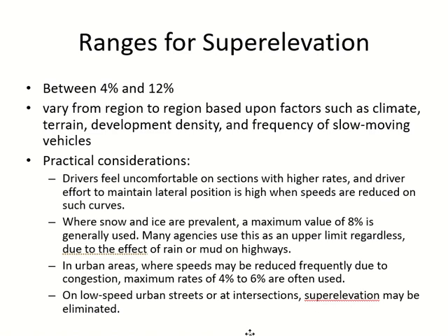Then the normal reactions are that you slow down, change your lane, or suddenly brake, and so on. Obviously that can have an impact on the road. You may not have a crash because of the design, but because the driver thinks the design is not correct. You may suddenly brake and get hit from the back. So driver appearance is also very important. We should avoid curves and superelevations that are not apparently good for the driver.